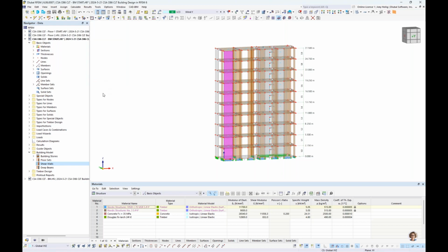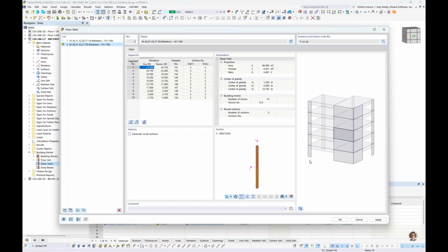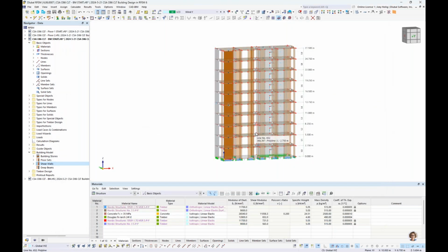as a shear wall. What the building model will do is to simply take these 2D surfaces and sum up the internal forces and present it to us as though it was a simple member, almost like a column spanning up through these shear walls. This is going to be much more user-friendly when we're designing our shear walls so that we can immediately see what are the total shear forces in this 2D surface, what are the total in-plane bending moments, and we'll see this in just a minute with our calculation.